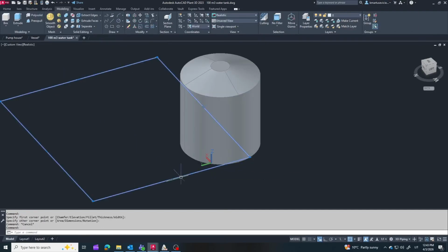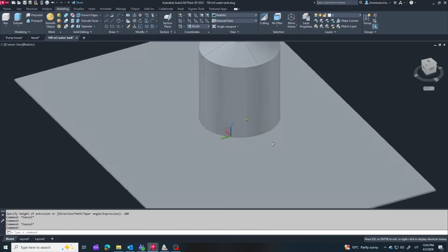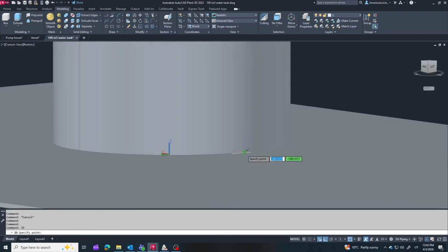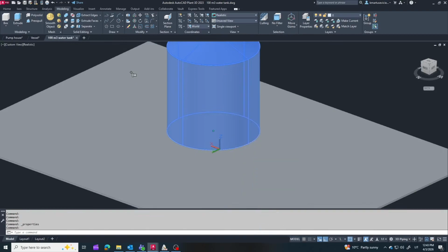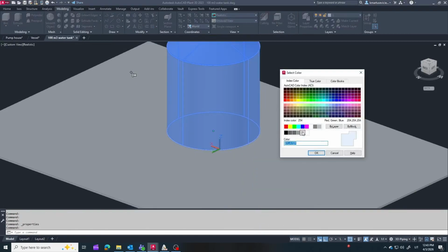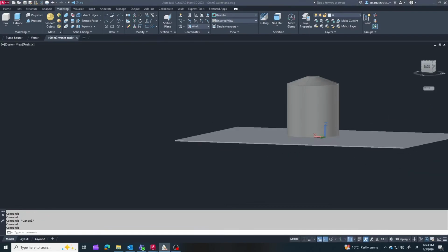On the other hand, if the tank is too wide and shallow, we start using more material, especially for the bottom and roof, which increases cost. That's why a 1-to-1 ratio between diameter and height is often the most efficient solution. It gives a good balance. Not too much pressure, not too much material, and overall better hydraulic behavior.